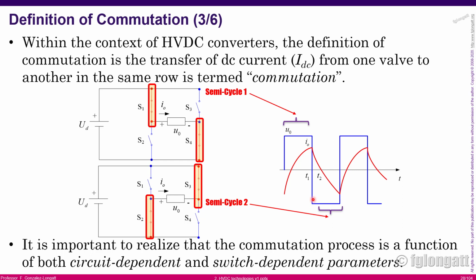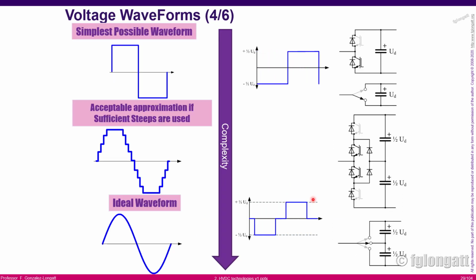In this case, we have switches that we have full control to open and close. And that depends on the electronic device that we are using. There are some devices that we can control closing the switch, but we don't have any control opening them. And we will talk about those devices in a few slides, okay? But for the very new technology, the voltage source converter, the closing and opening of those switches can be controlled, okay? Now let's see this.